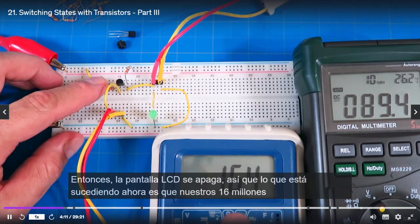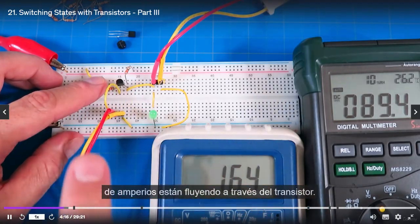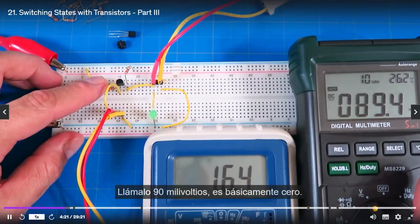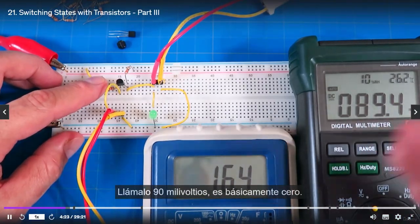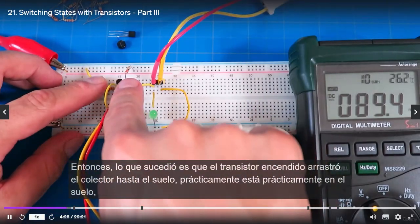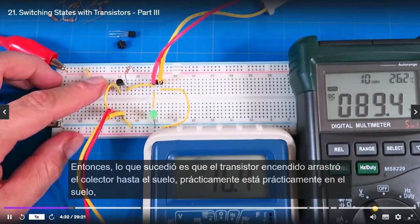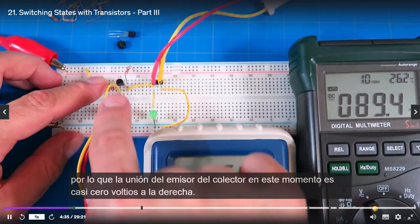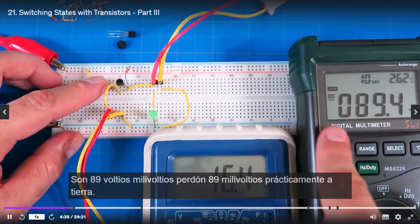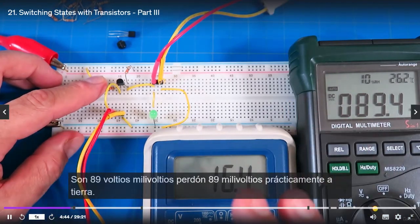So what's happening now is our full 16 milliamps are flowing through the transistor. Look at the voltage on the collector. It's 89, call it 90 millivolts. It's basically zero. There's 0 volts over this LED now because it's right at the collector. So the transistor turned on and dragged the collector practically all the way down to ground. The collector emitter junction right now is almost 0 volts, 89 millivolts, practically down to ground.